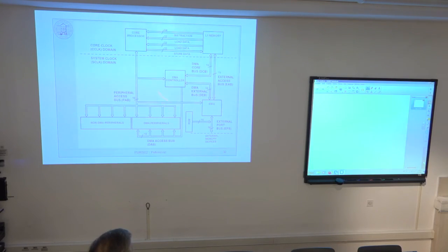So you simply program this DMA controller that immediately once a new value is available on some DMA supported peripheral, this value would be read out from the input register and automatically written into memory to the corresponding location to the address that is part of this DMA controller.